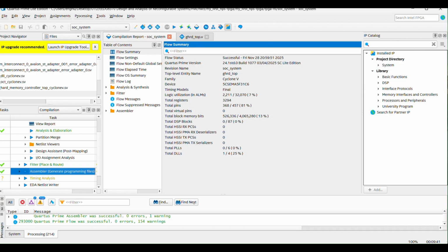And if we download the SOF file now, we are wiping out and replacing everything that was previously running in the FPGA, including the VGA hardware. And because we need the FPGA VGA monitor to run the C program on the Linux terminal, we're gonna keep it as is now and go to the C part of the project.